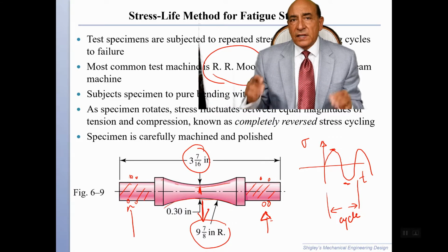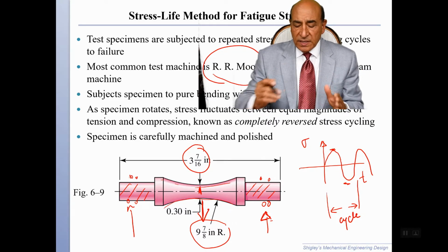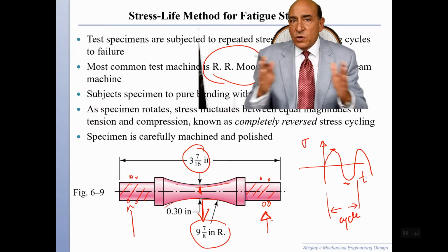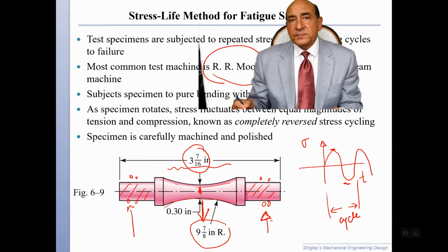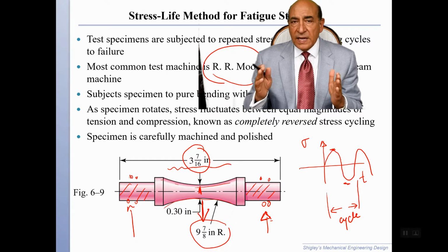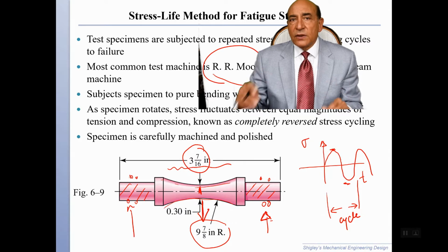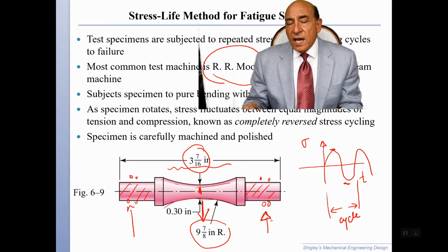So when we have a constant load on the material and reactions, we obtain a moment, and the moment is distributed over this middle section. We can arrange the loading so that the moment on the middle section is constant. So we can have a 4-point bend test where the middle area has a constant moment.